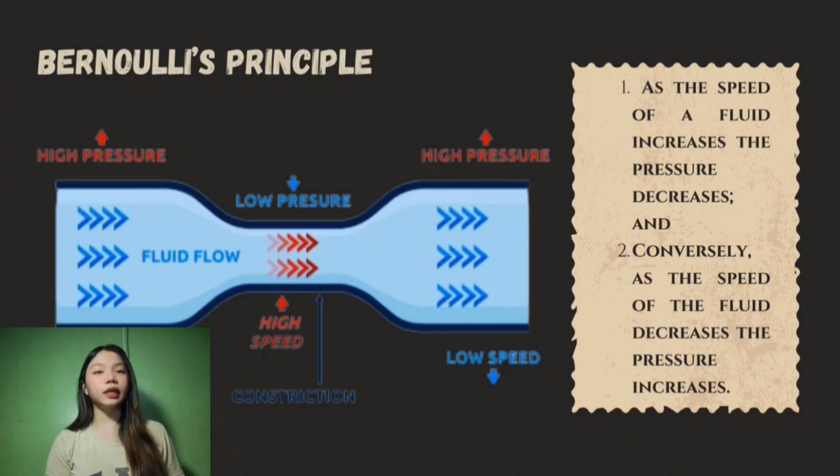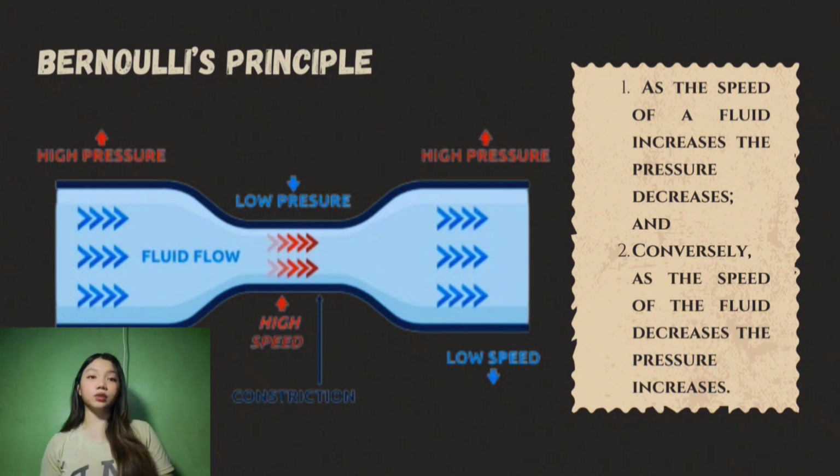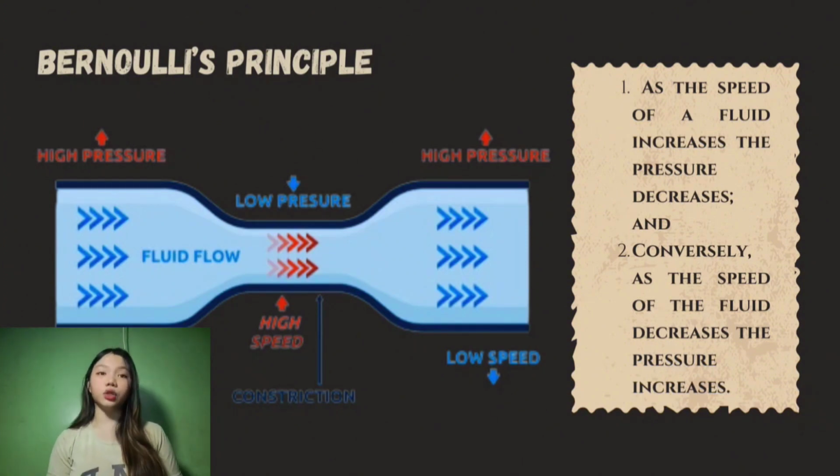Now, here we see a diagram of a pipeline with a fluid flowing through it. This could either be a liquid or a gas. And we're going to assume that the rate of flow is constant throughout the system. If we assume that, then where the cross-sectional area is smaller, the fluid tends to move faster to get through. So, we've got a low velocity region and a high velocity region, then going back to a low velocity region, because this is a Bernoulli tube.